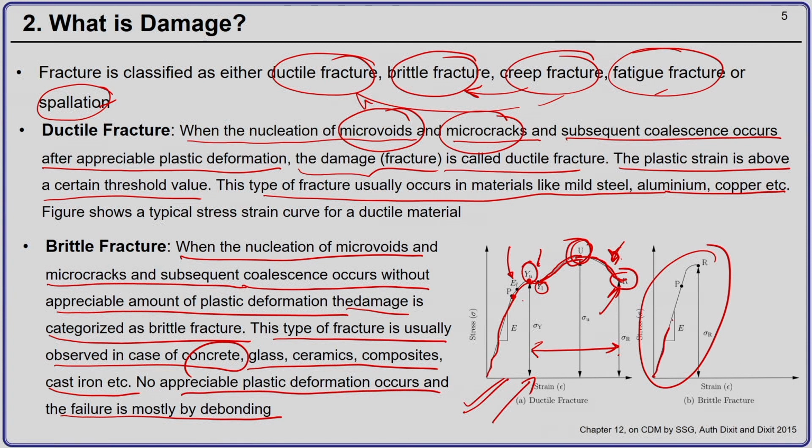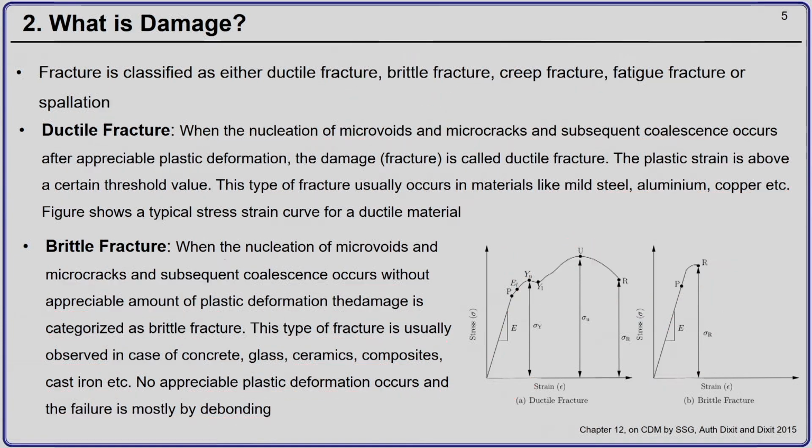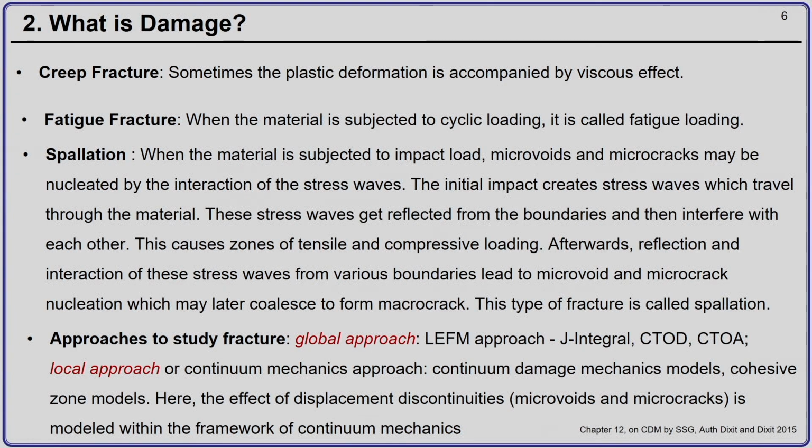So, there is elastic deformation, and immediately after a small amount of plastic deformation, the material fails. So, there is no considerable plastic deformation in brittle fracture. Okay. Now, we quickly look into what is meant by creep fracture.